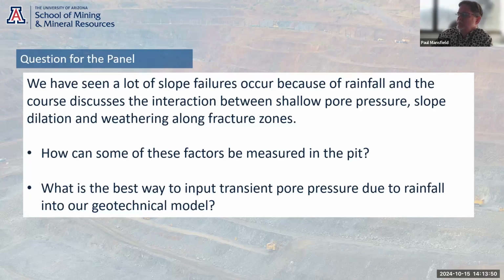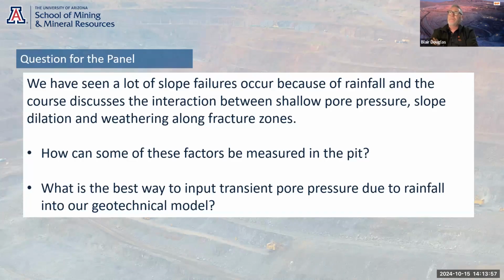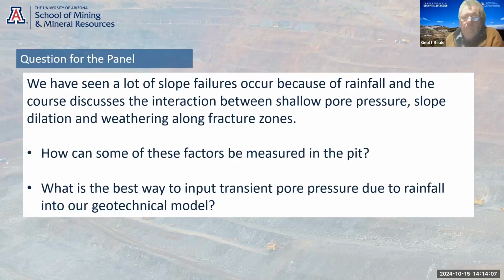Just to add to that, Paul, Blair here from BHP. We've had a number of failures related to this type of mechanism. Now, they're very difficult to measure in some cases. Actually, piezometers don't pick them up because you're looking at very localized recharge events, maybe through tension cracks, maybe through other geological features.